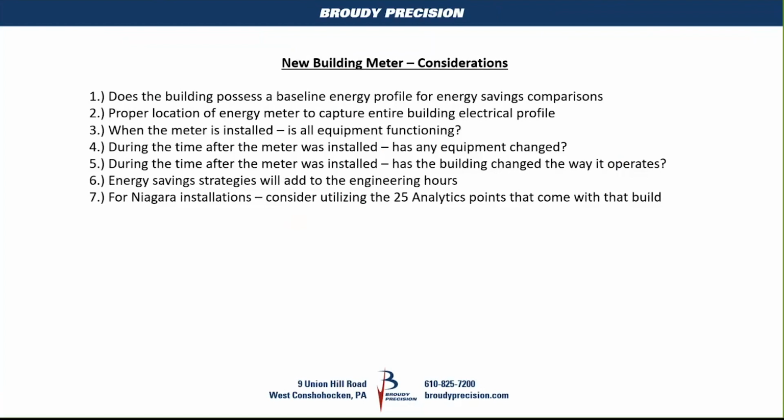I talked about the proper location of the energy meter to capture the entire building electrical profile. I've seen guys put in meters downstream because they didn't know any better. And you didn't capture the entire utility meter, it only captured part of the building. So, well, why doesn't my meter read what the utility meter reads? I'm not even close. Well, that's because you didn't capture the whole building. Seen that happen a bunch of times. So we need to be careful about where we're installing our meters.